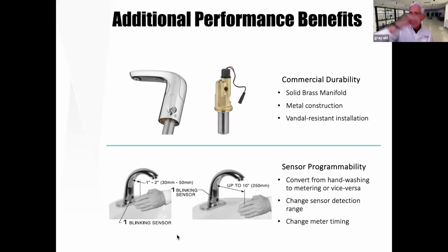So if I go 48 hours over a weekend at a healthcare facility, I can program in there that each day it flushes out the water, so that the water does not sit in the lines and have a chance to be stagnant. Those are the kind of options. We use electronics a lot in school applications, where you have that void, say over a long winter break or a long summer break. You can set a single activation just to keep water flowing. Yep, all good stuff.